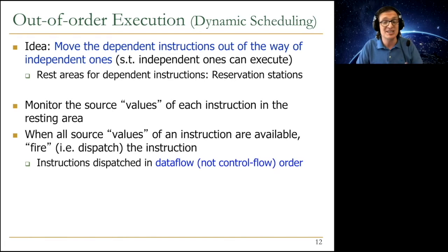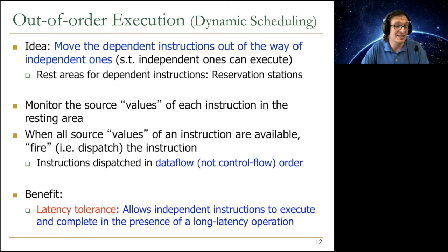Instructions are now dispatched in data flow and not control flow order, right? So the benefit is latency tolerance. This allows independent instructions to execute and complete in the presence of a long latency operation, as you will see.